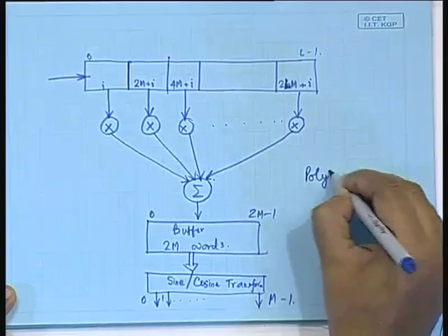Okay. So, that is how it realizes a polyphase filter. You are taking the prototype low pass filter as the basis, and then by multiplying it with the complex exponentials of the center frequencies, you are obtaining the different filter banks through a polyphase filter technique.